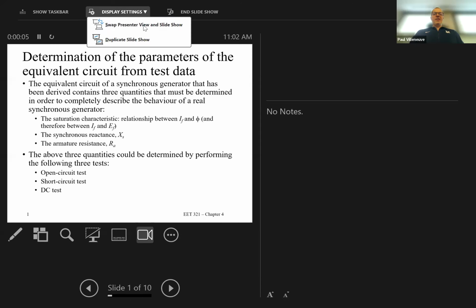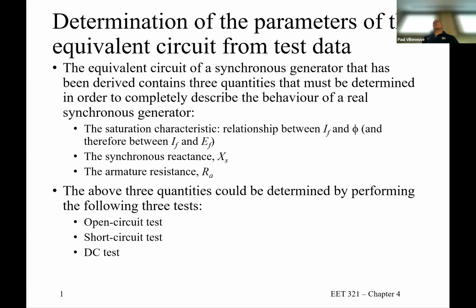So how do we determine these parameters? Well, in transformers, we did open circuit and no load tests and load loss tests, sometimes called open circuit and short circuit tests. That's pretty much all the testing that we can do with any electrical piece of equipment. Some people will tell you to run frequency response and do all these different things.